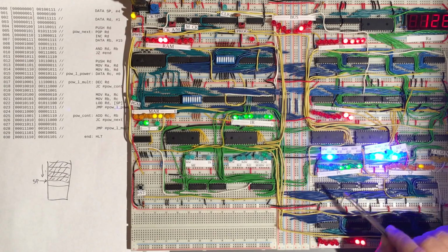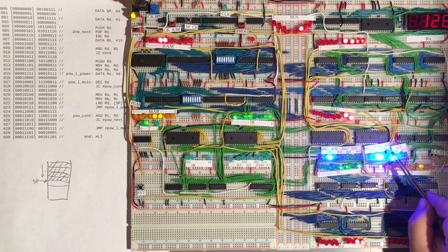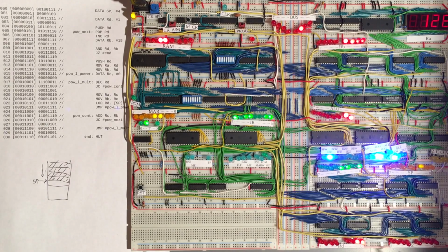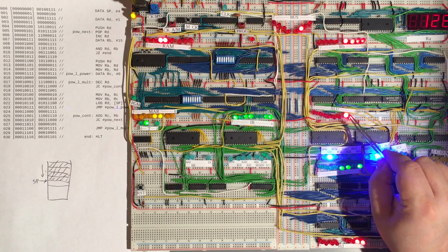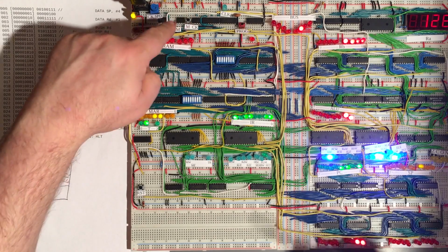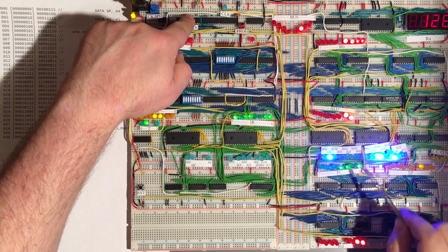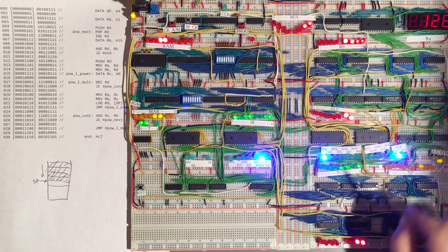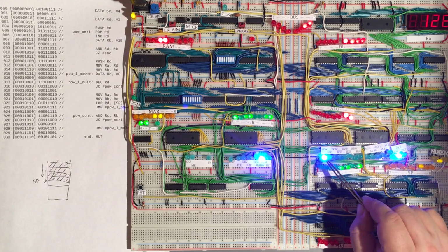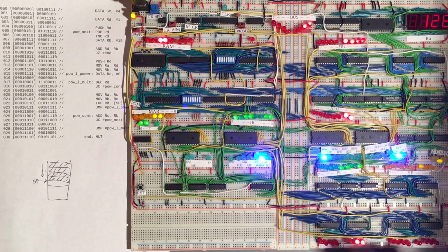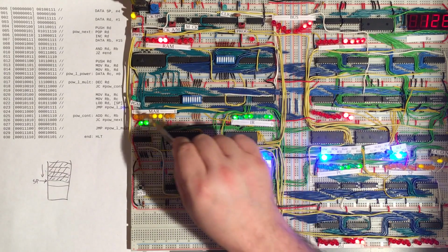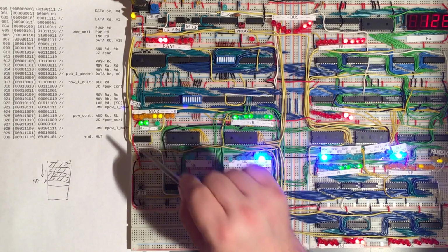So we'll be subtracting 1 from the final result, and we're not using the B register, we're using the hard-coded value of 0. This means, in essence, decrease whatever's coming in on the bus by 1. And so we'll have a 3, and once again, it's actually already there, but that's pure coincidence in this case. So it will calculate that 3, there it is, and then that 3 will be written finally into both the stack pointer, so that the stack pointer itself has been decreased, but also into the memory address register on T3 of the push instruction.